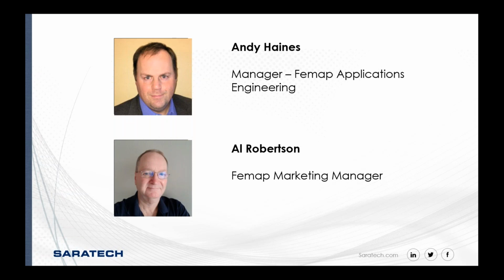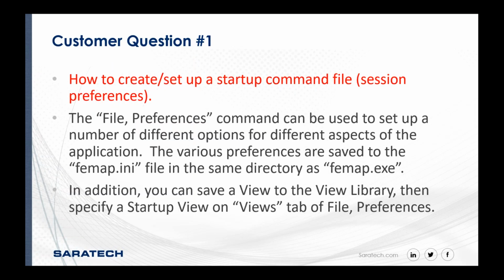All right, great. So we got a number of questions, I think 10 or 12 overall, so we're just going to go through them one at a time. The question was how do you set up a startup command file, a session preference? I hope most of you have found out by now that you can go to the File Preferences command, and there are a number of tabs on there that control different aspects of the FEMAP application.